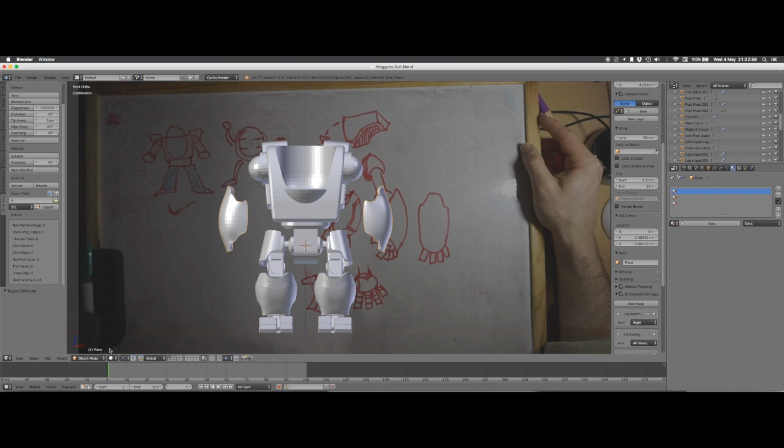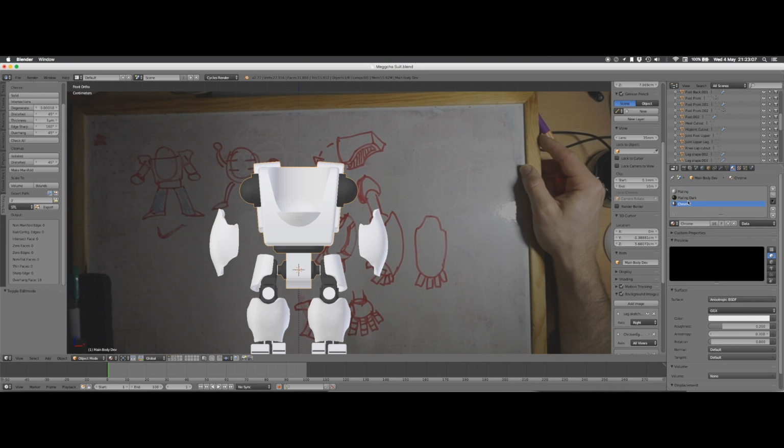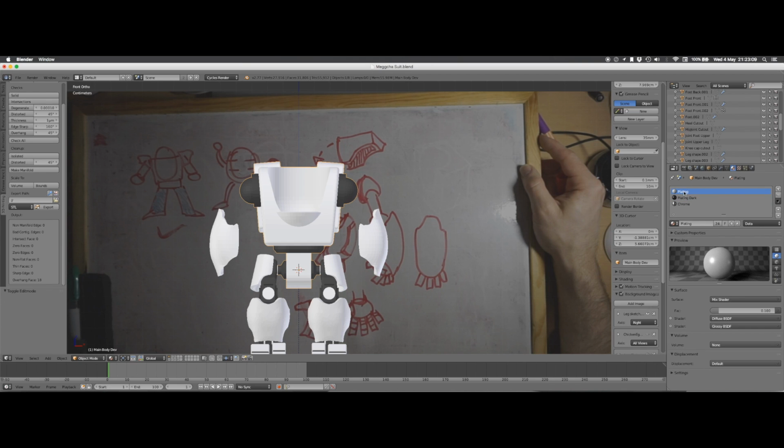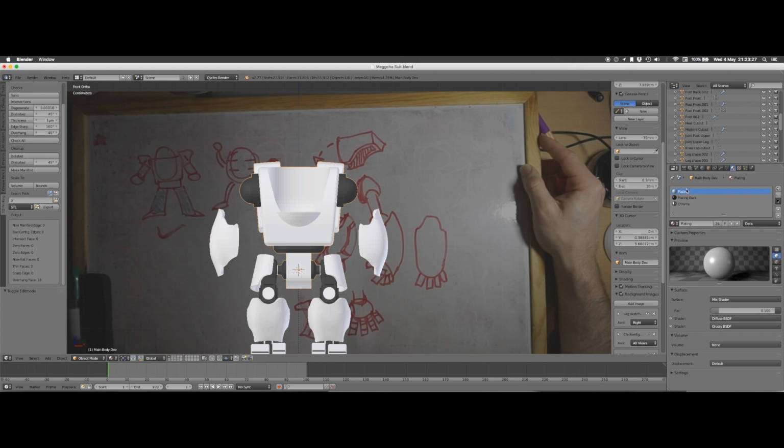If you've, like I have, assigned material colours to different parts of the body, as you can see here, I've got the three main ones I use on this model, and on this they're not there yet. If you do a Boolean operation and you've only got one material set, it'll just pick whatever the first material in the list would be.